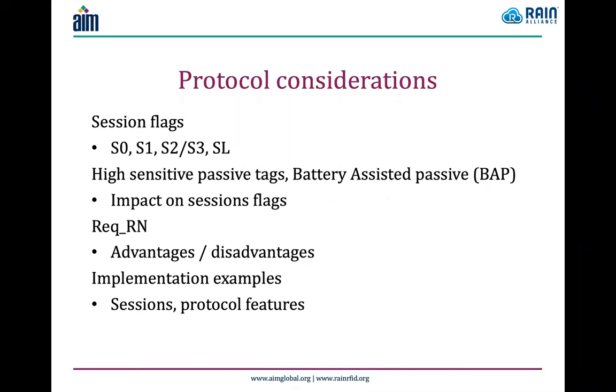Then there is also a topic on these highly sensitive passive tags and battery-assisted passive tags. What is the impact on the session flags? What does it mean? Because they have a significantly longer range. For the battery-assisted passive tags, they basically don't lose power. So how do you ensure that you can properly handle those tags?